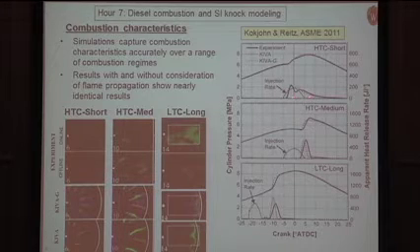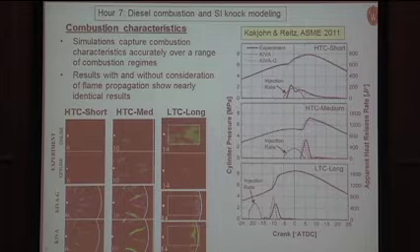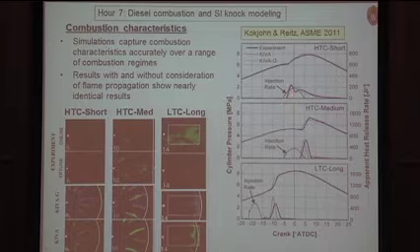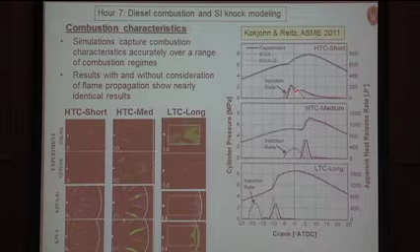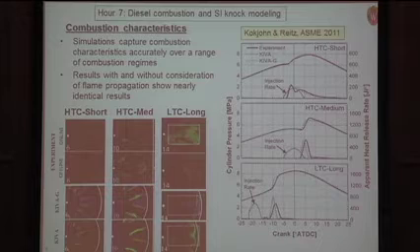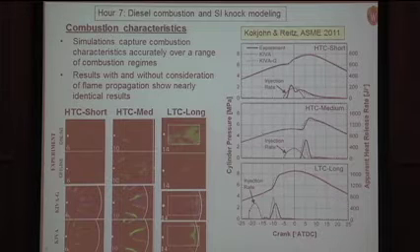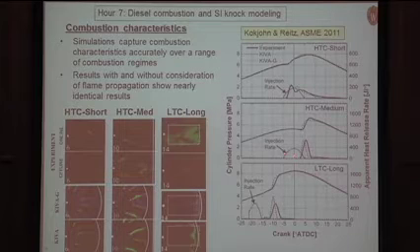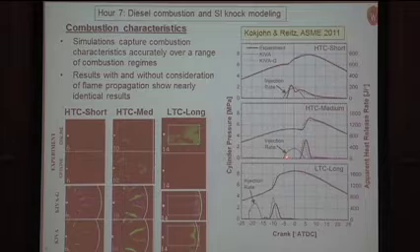And the end of injection, you can see the injections occurring about 5 degrees before top dead center. The other thing that you see here is the heat release rate. So we can see the evidence of that premixed burn and then the diffusion burn for this short high temperature combustion. Good agreement with the measured and predicted cylinder pressures. So when we go to a lower intake temperature and now longer ignition delays, you see injection again starting about 5 degrees before top dead center here.